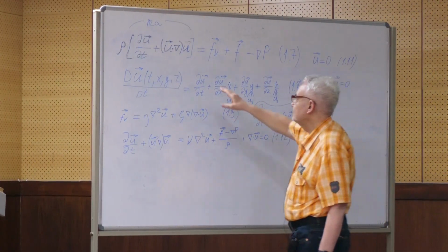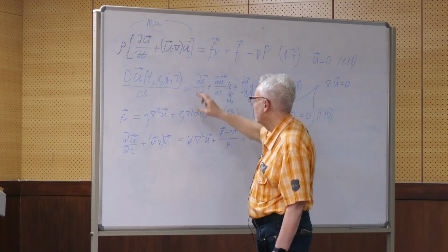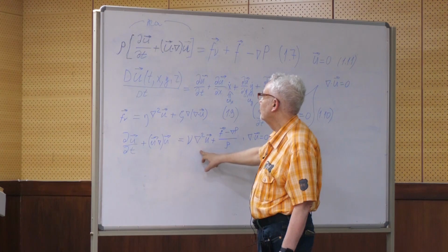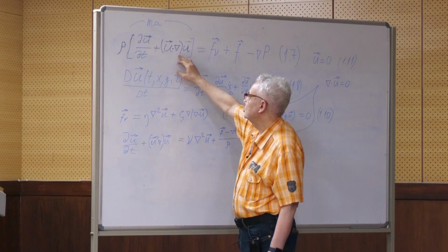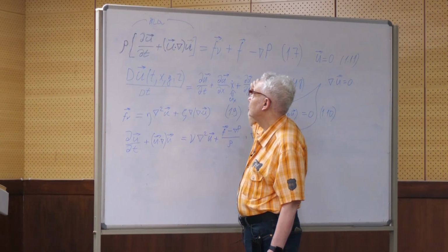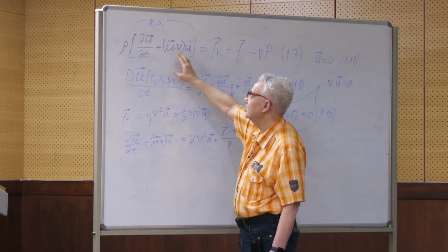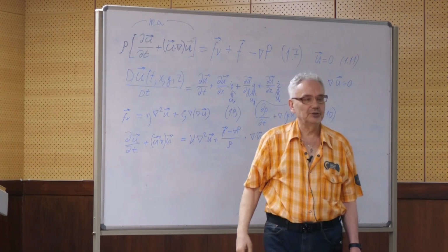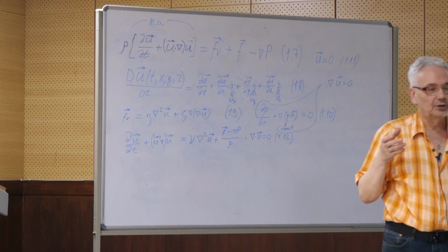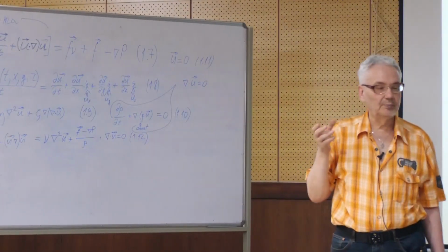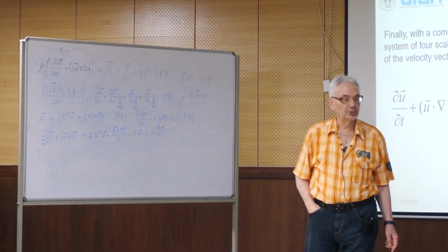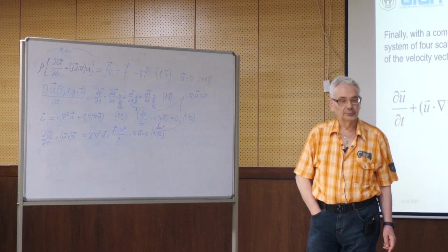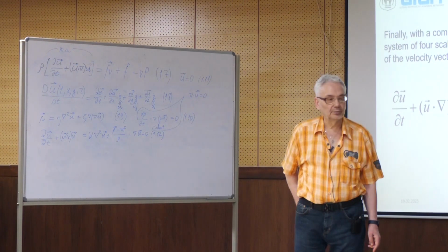And of course, the simplest estimation of the turbulence: if we compare this term and this viscosity term, you see that if you take this u, and because here there are derivatives, some characteristic size, you can directly have the estimation of the turbulence. You just take the average velocity, multiply it by the typical distance, and in order of magnitude, you obtain the turbulent viscosity. So it comes directly from this term.